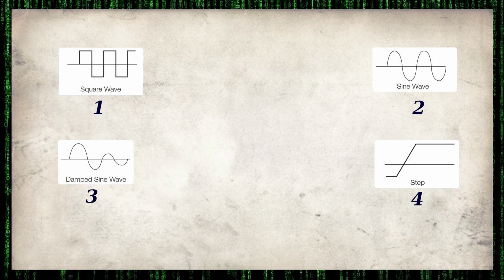But once we climb back up again, that next climb over the x-axis is very low. That's not even 2 volts. So that could be considered not a clear 0, and not a clear 1. So you can make a decision here about what you want to do with it. Do you want to allow a certain level of error or latitude? Like in this case, we might say, okay, 1.5 is okay. That is also considered a positive. Or is this an error signal, and it has got to be resent?